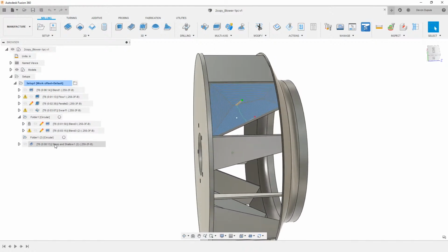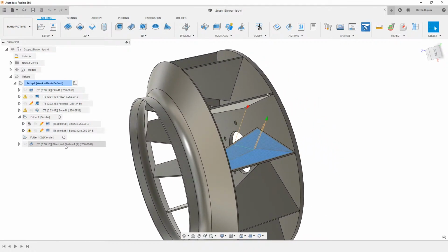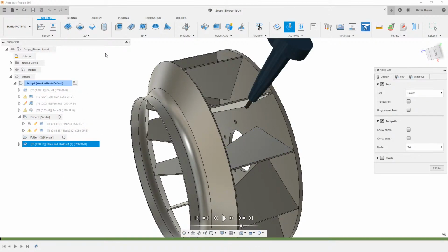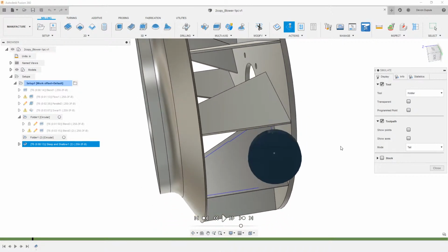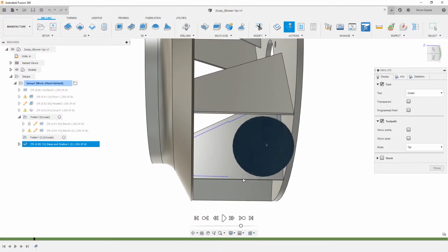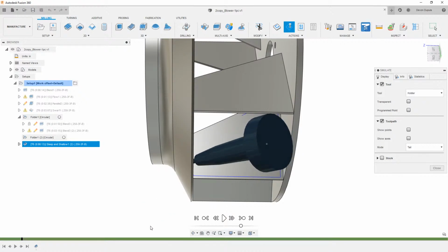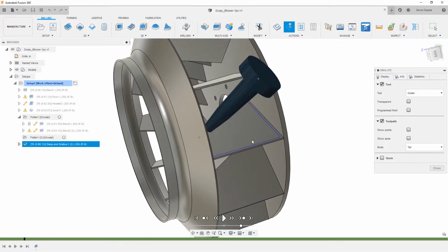But with this, so this is steep and shallow, and we're going to go into this a little bit more, but this is one of the things you can do with the new steep and shallow toolpath. So if I come in here into simulate and we hit play on this, we'll see this does a really good job of machining, and there are obviously some undercut faces on here. So if I look normal to that surface of my toolpath here, and we drag this back, we see my tool cutting underneath my part and going over, making this pretty difficult part fairly easy to do inside of Fusion.